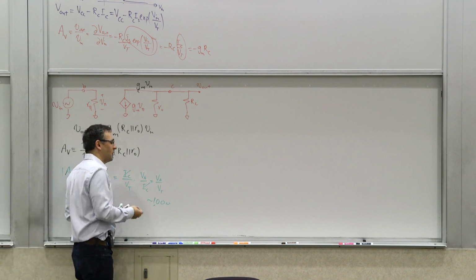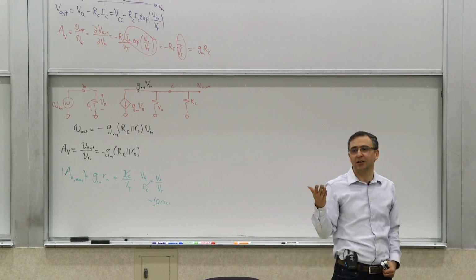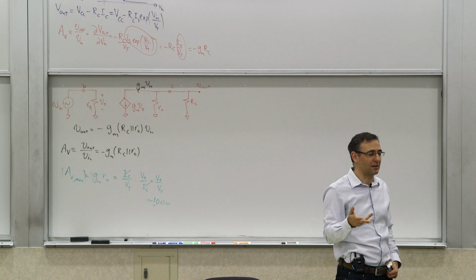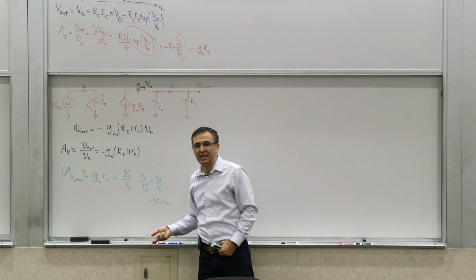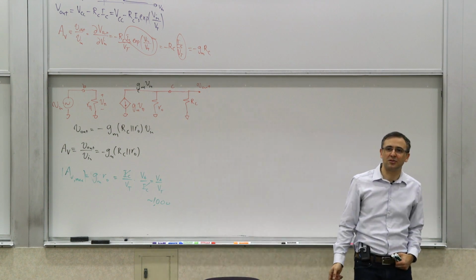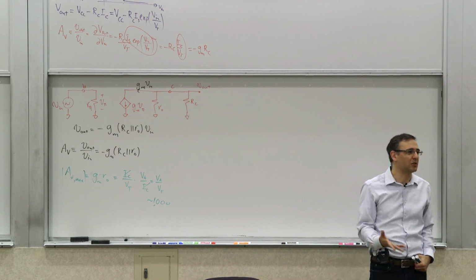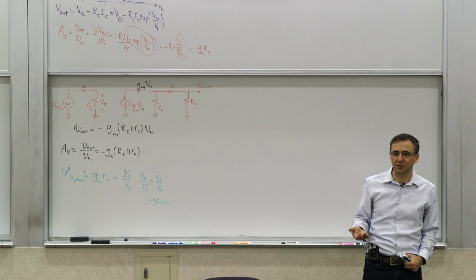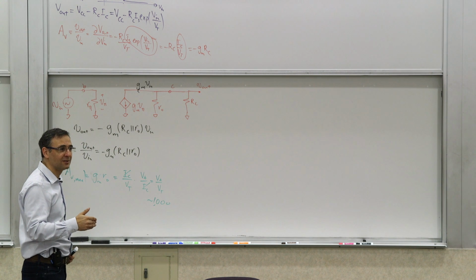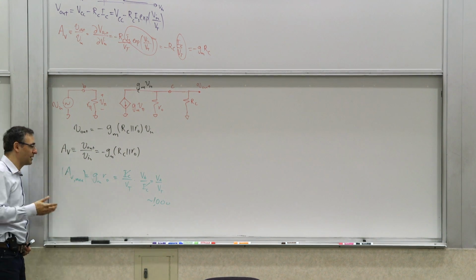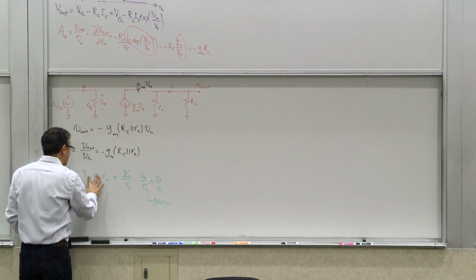If you're given a transistor to design with, and gain is relevant to what you're designing, one of the things you should calculate first is its VA, and from that the maximum intrinsic gain of this transistor. That gives you a sense of what you can or cannot do with what level of sophistication and complexity. And there are lots of things you can do if you're willing to make it sufficiently complex and pay the price for it. But that's what we call the maximum intrinsic gain of the transistor.